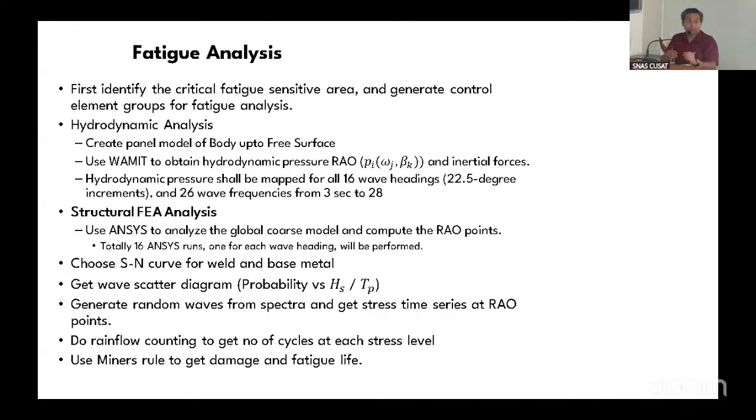So essentially you have the pressure arrays, and then you run ANSYS. In a fatigue analysis, you need to do a time series, but we actually do a trick. The reason we can do this trick is that it's a linear static analysis. Essentially, the structure is linear static. The only non-linear part is the mooring lines, but we don't model the mooring lines. We just put forces or linear springs there. The advantage of doing this is that you can do one static analysis.